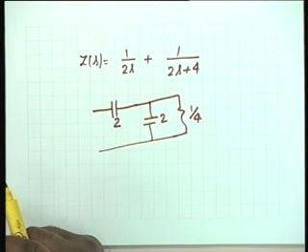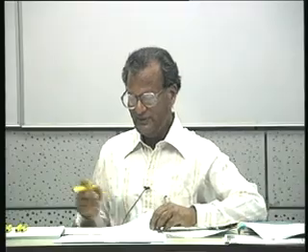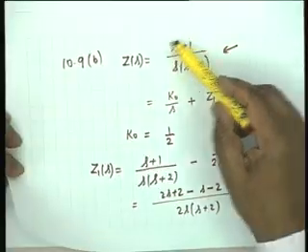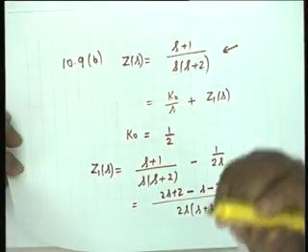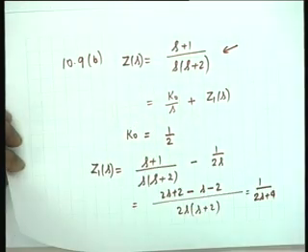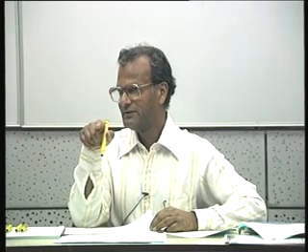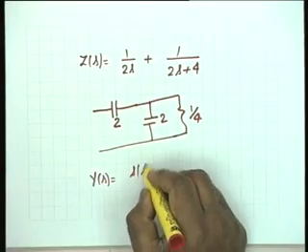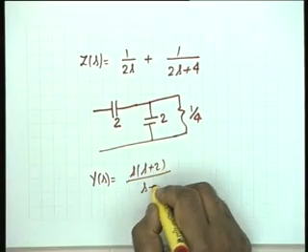Question: is there any other way you could do it, just by looking at poles on the j omega axis? Let's look at the function again. Could we do it in some other obvious way? Instead of Z, suppose we took the Y, the reciprocal of this. Then what would we have got? Y of s would be equal to s into (s plus 2) divided by (s plus 1).